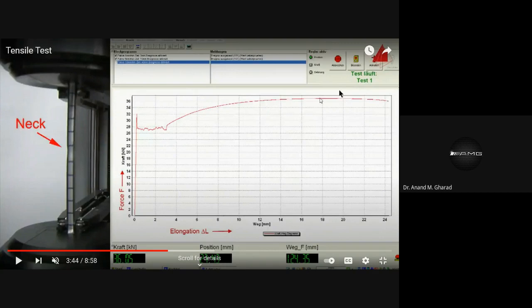And up to this point where the stress is maximum, if we are in a position to allow that material to use its capacity, then it is the best part. This is the advantage that is being taken in your limit state design method, LSD or LSM, whatever you call it. This is the advantage. The material is allowed to deform up to its maximum capacity.